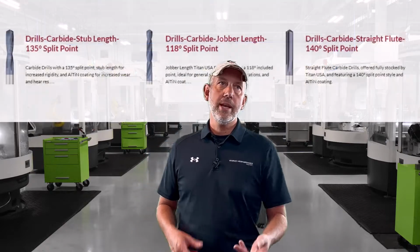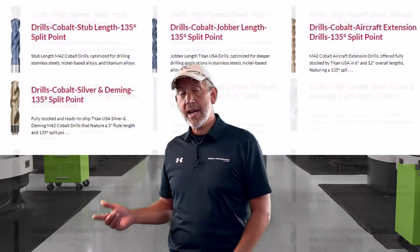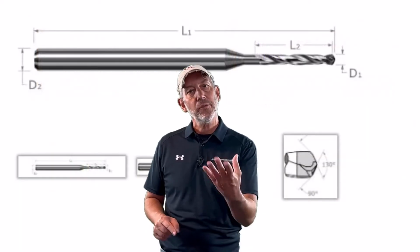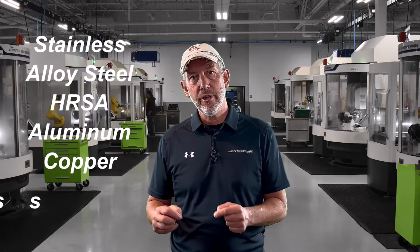So drills come in all shapes, sizes, helix angles, point geometries. Some are split point, some are not split point. Some are high-speed steel, some are powdered metal, and then you get into carbide, and you can even get into PCD tipped and stuff, depending on what material you're actually cutting. And so that is very important to start this episode off on drills with the material that you're drilling. Because we just talked about the point geometry briefly, and the point geometry is critical for that axial force, but it's also critical because all the different types of materials that we're drilling into make a different chip.